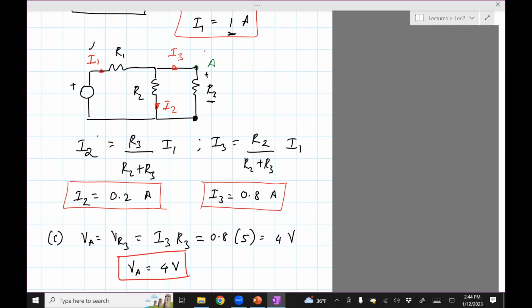If you know that there is some parasitic resistance which is causing a voltage drop, then you can use a simple multimeter, which has a voltmeter in it, to debug the problem. So using the voltmeter function is kind of central to debugging a circuit. And that's why you want to know how to use these rules and analyze the circuit. Voltage drop is one of the most powerful ways of debugging a complicated circuit. Okay, we have time for one more question and then we'll stop.